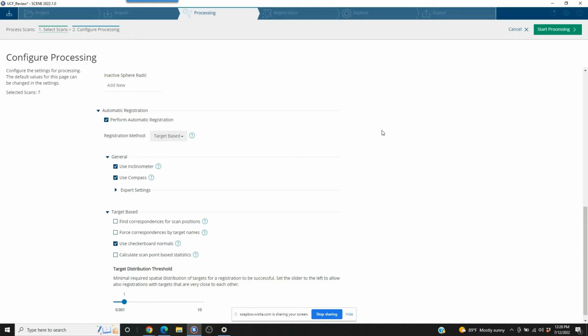So the ones that are furthest away from your scanner now, you would move to the front, the direction that you're scanning, and you're going to leave the three that were closest to you, leave them there. When the scanner then does the next scan, this is pulled in here in the pre-processing method of registration.